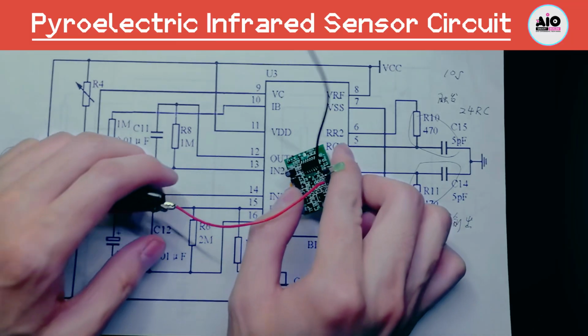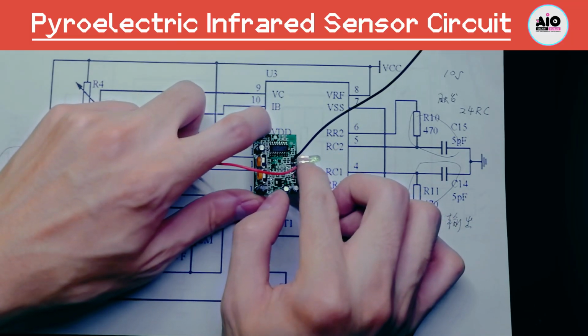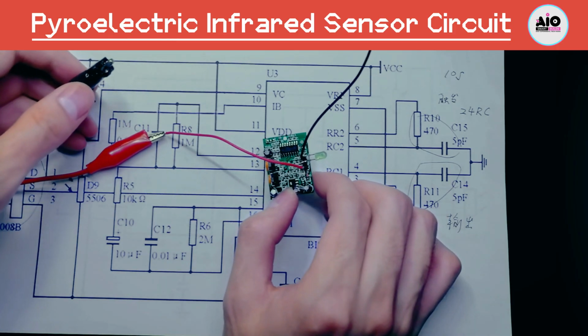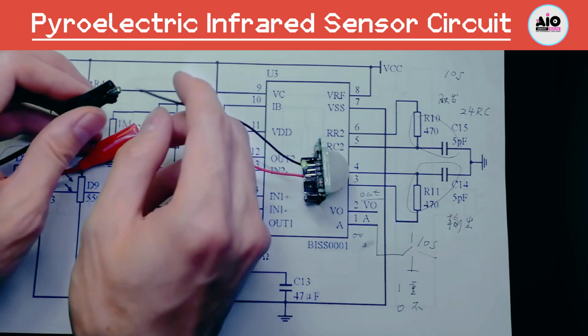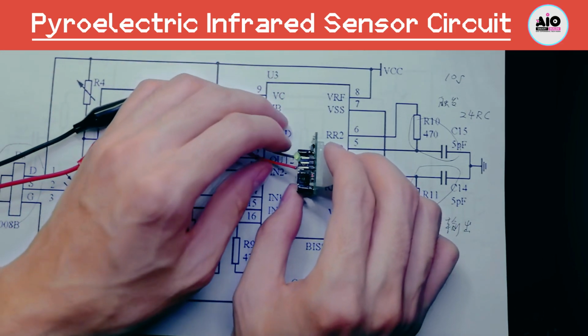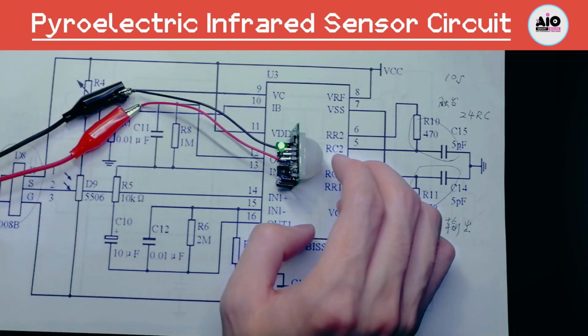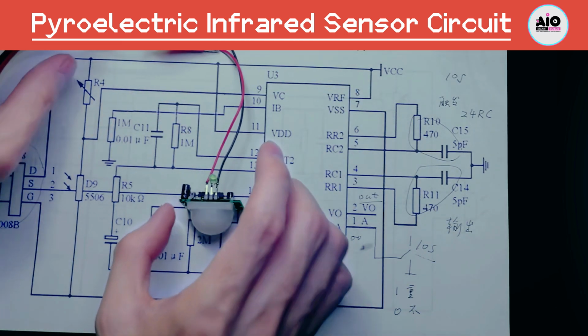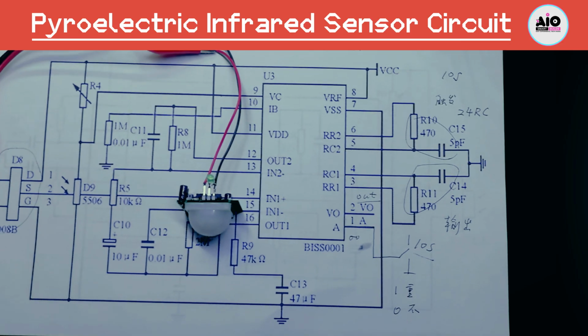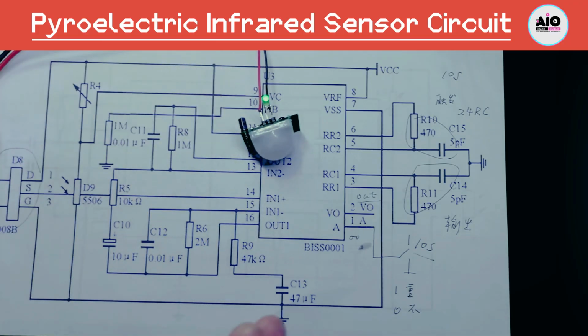Here we just use an LED to demonstrate its working process. We pass the voltage to this circuit. The working voltage of the chip is in the range of 3 to 5 volts. On this PCB there is a circuit with a DC part, so its input voltage range becomes wider. What we are currently connected to is a working voltage of about 4.0 volts. As for the delay time of its status, I adjusted the time to be relatively short, about 1 to 2 seconds, and then trigger it repeatedly.